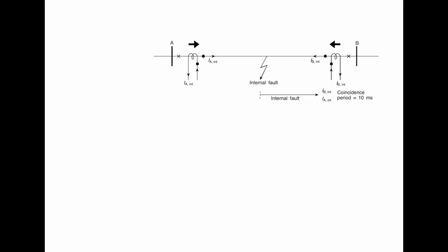Now let us take a case, let us assume delta to be 20 degrees, then any phase shift between 0 and plus minus 160 degrees will indicate an internal fault. Let us suppose that delta is 20 degrees. Now let us draw a diagram.